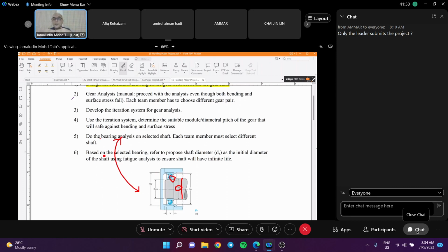That will lead you to your initial geometrical properties of the shaft, where you have to put the bearings, what the load is, and you can predict the radial load and the thrust. For a spur gear there is no thrust load, right? However, I did mention you need to assume the smaller radial load with thrust load. Otherwise you always have many possible solutions.